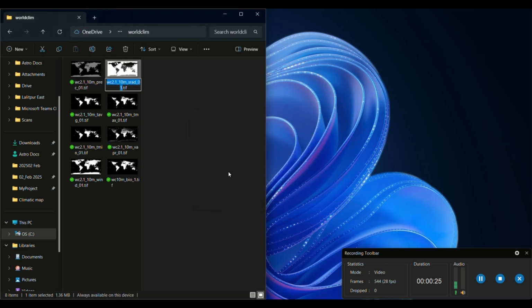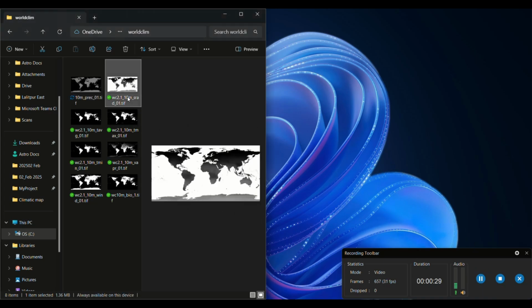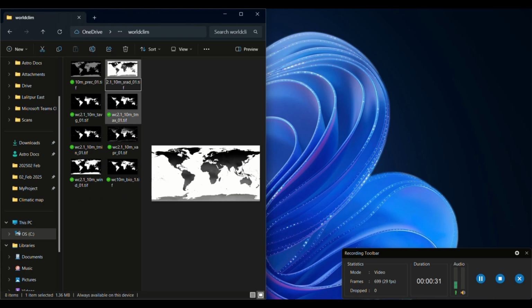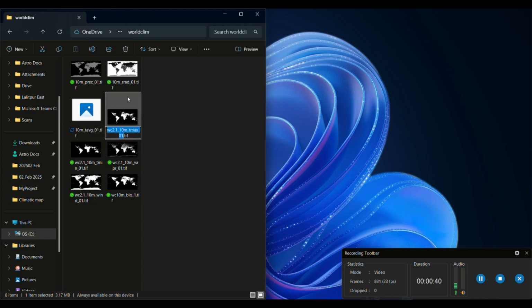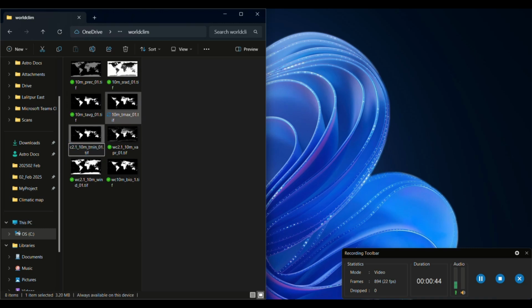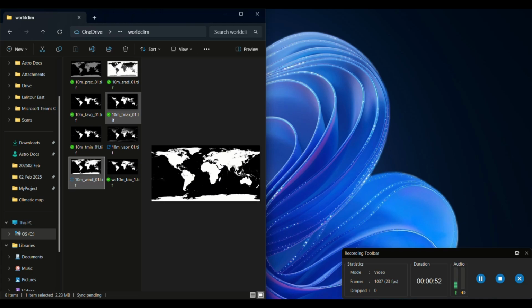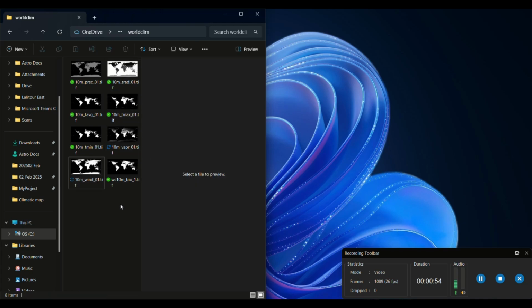Okay, I got an error because it's open, but yeah, do the same for every file. Remove the dot from the file name, because ArcGIS does not accept that kind of file name. So I've done it for every file. Now you can continue.